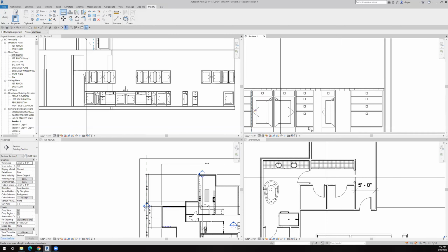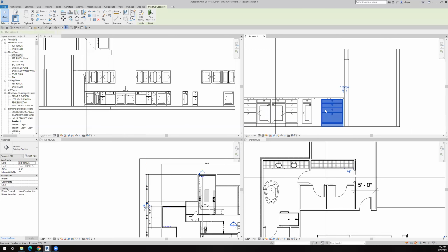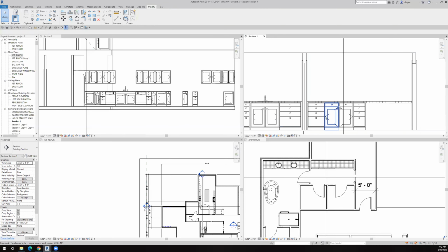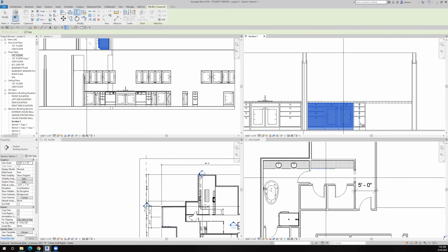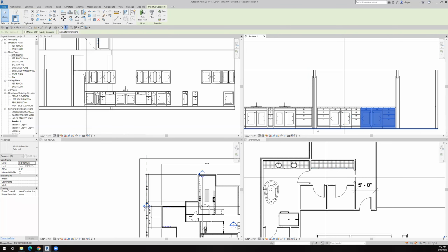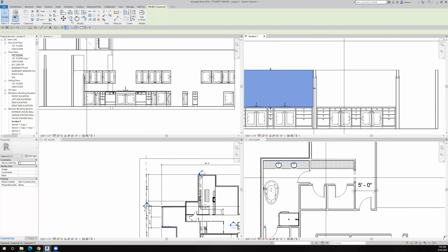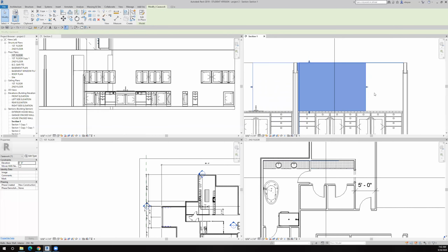That looks good. Now I can actually delete these and use the power of Revit and just click here, here, and here, and then mirror all of those about the midpoint of that. And we're looking good in terms of everything except, let's see if I can copy this over. I'm going to copy it over to there and then just drag it, face of the wall to the face of the wall. Oops.